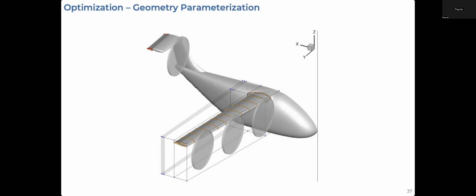And the reason for this is because the vehicle is not very well balanced in its baseline design. So the structure was optimized to increase weight towards the tail to decrease trim drag in the optimization. Most of the wing panels reach the minimal allowable thickness, and the tail mass is used to improve the overall vehicle trim. To highlight the optimization history, we can see that the convergence tolerances for both optimality and feasibility decreased significantly down to 1e-6, where the optimization exited successfully.